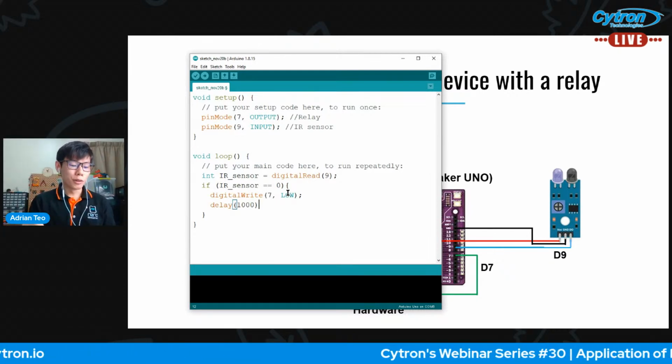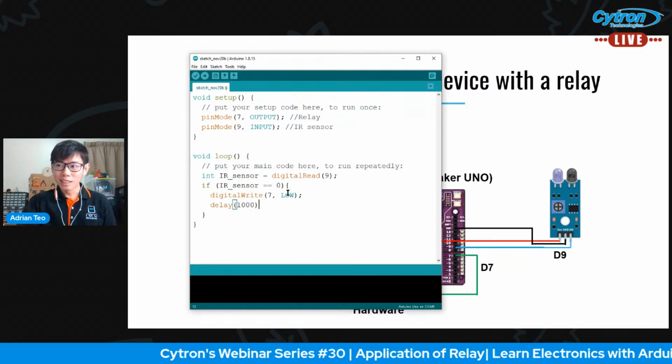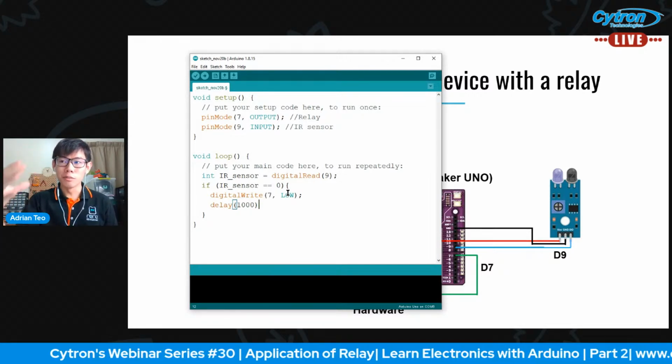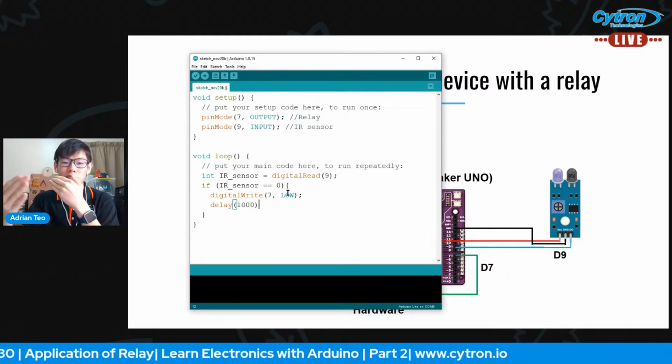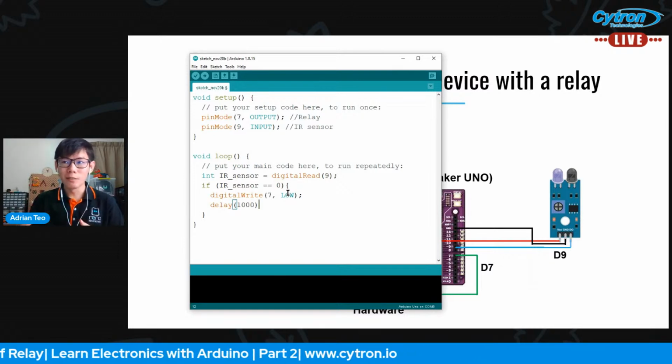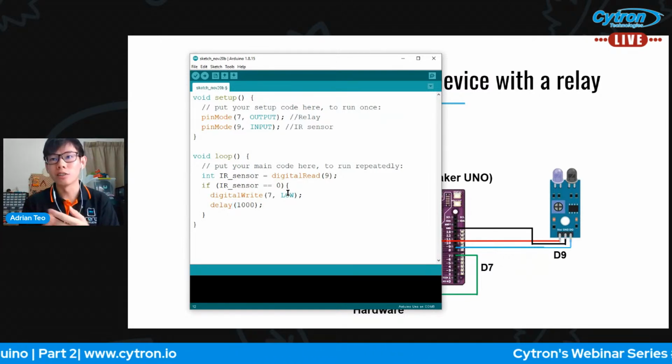If you go to your office or any other place, when you scan your card, it opens the door and then it remains open for a period of time, maybe 5 seconds, 10 seconds, then it locks again. So you need a delay for that. If you don't delay, then it will just open and close and then lock the door back again.